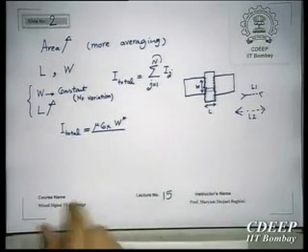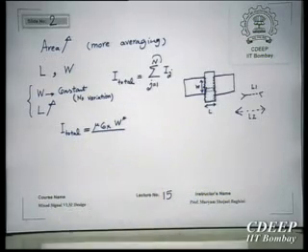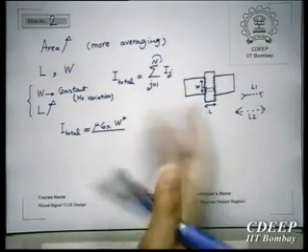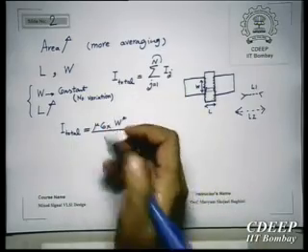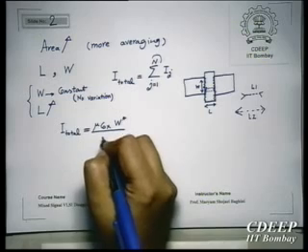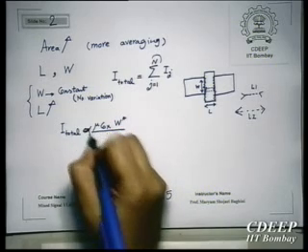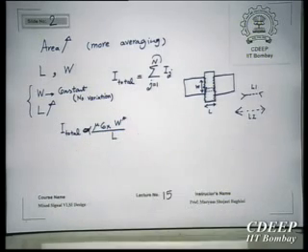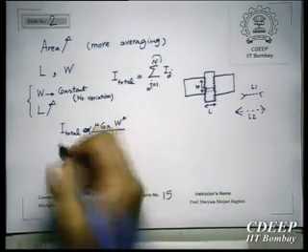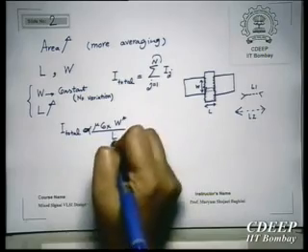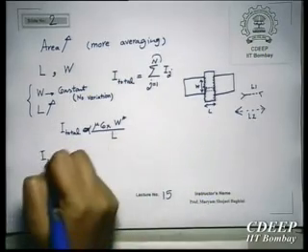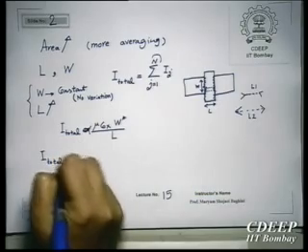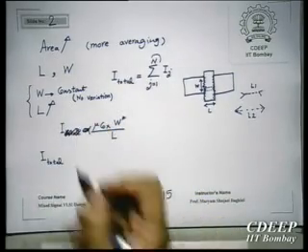Suppose this is the current mu C ox W star, and some bias I also have, VGS minus VT, or it is in saturation region, whatever. What is important is I total is proportional to this ratio, right? According to the bias for these transistors, if I want to write real current, in fact we should write this I is proportional to this.